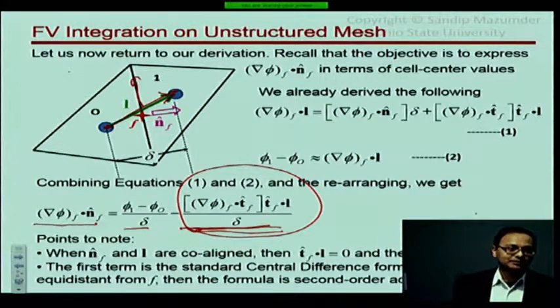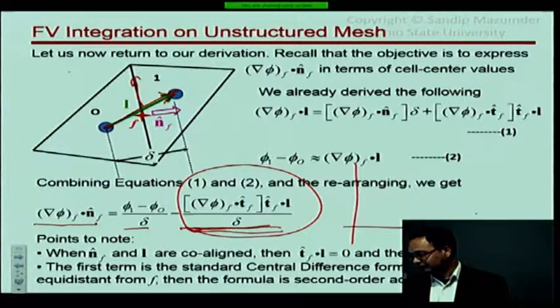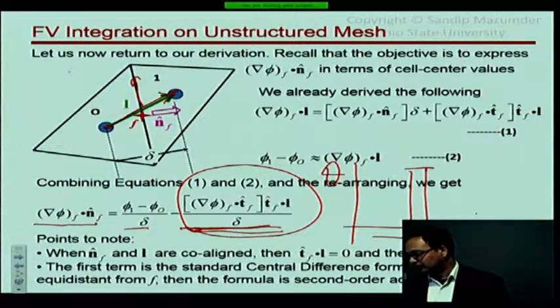Okay? And most mesh generators now give you a lot of information, basically statistics on the angles essentially. Okay, so if you look at the histograms they plot, typically it'll look like this. Okay, so this is angle theta, and this is, of course, number of cells. So it'll look like that.